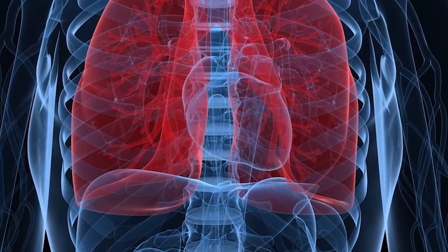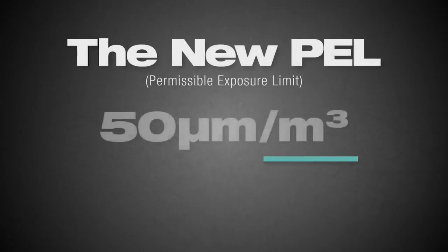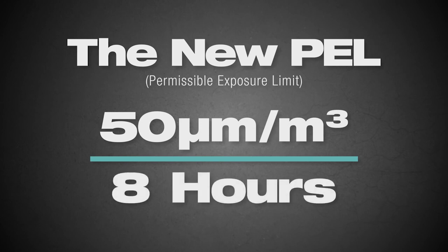Exposure to respirable silica dust may lead to lung disease, respiratory disease, lung cancer, and kidney disease. This is why OSHA has reduced the permissible exposure limit to 50 micrograms per cubic meter of air as a time-weighted average of 8 hours.